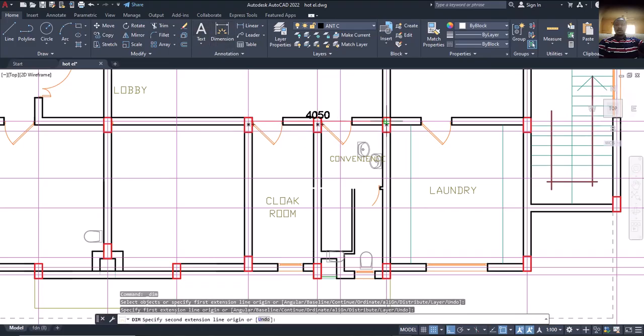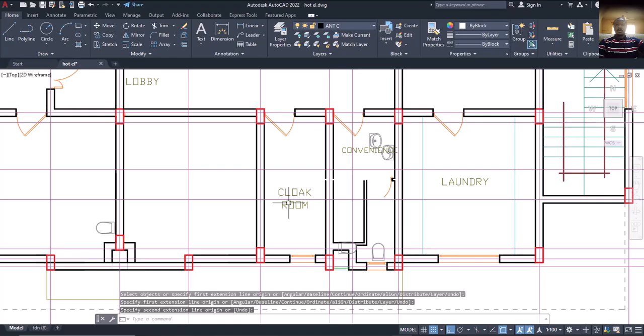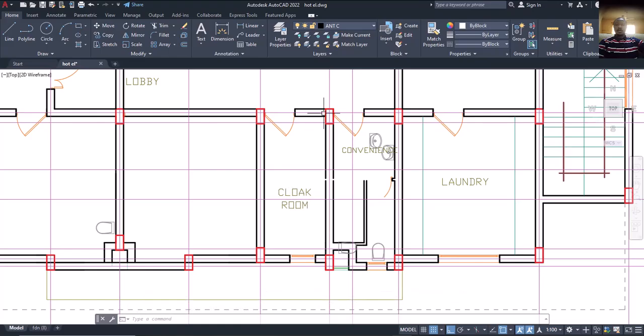From here, this is 4 point something, and from here 4 point something. So which means this place is less than 30 square meters. That means we can now have a slab, a wall sitting on this slab here, isn't it? So we can have a beam from here like this, and also a beam coming here like this. So we now have this kind of shape of a slab. Is that okay? Our wall, we're going to sit on this.